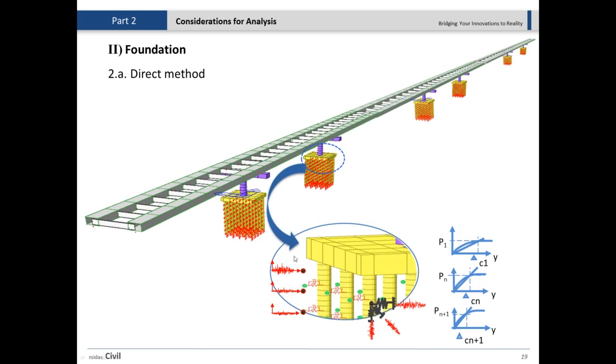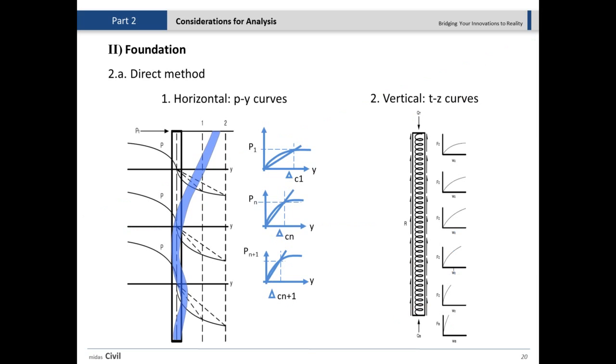As you can see here, I have this forcing function applied at this location, and a different one at a different location. That's pretty important for being more accurate, and to consider different forcing functions if you have a pretty long bridge where the site is changing and the soil layers are changing, or if you have a deep pile.